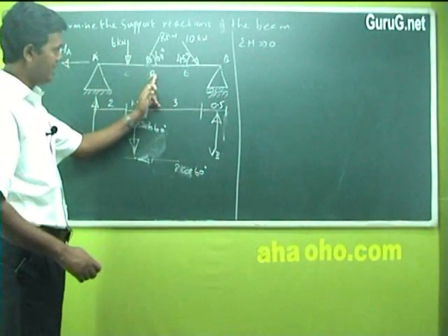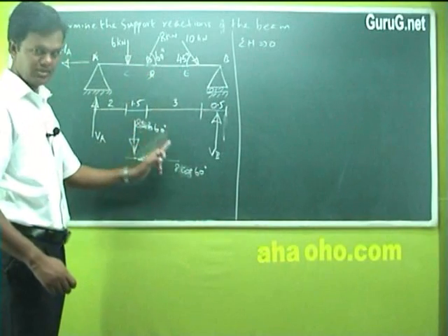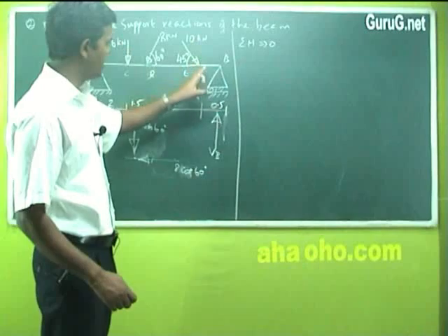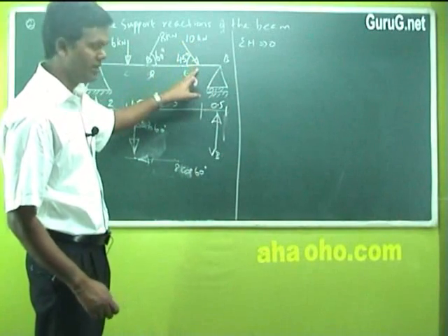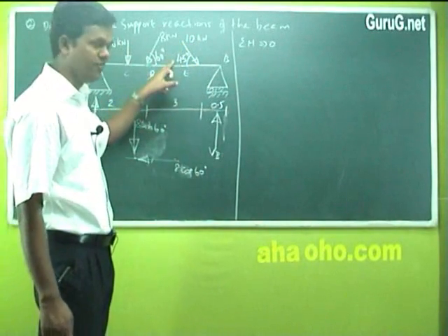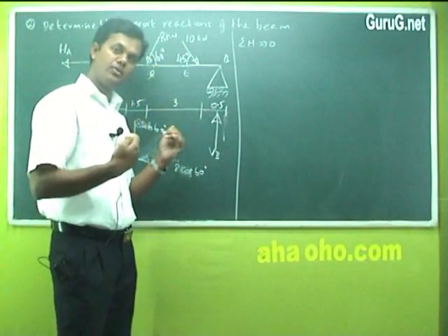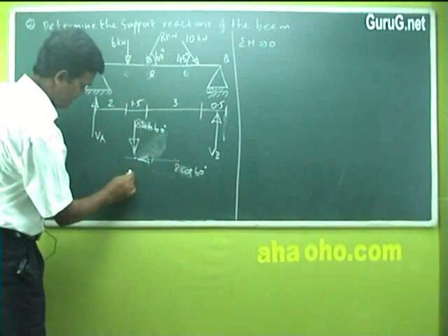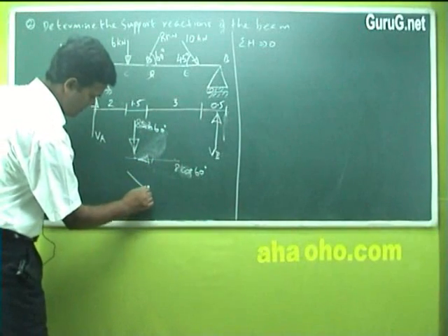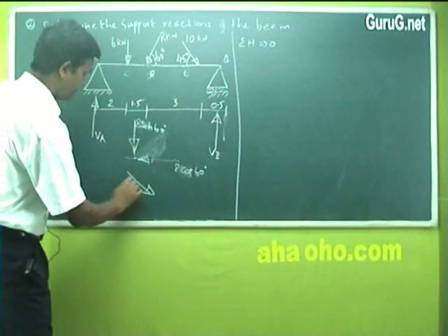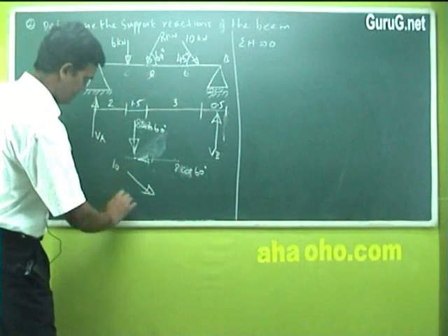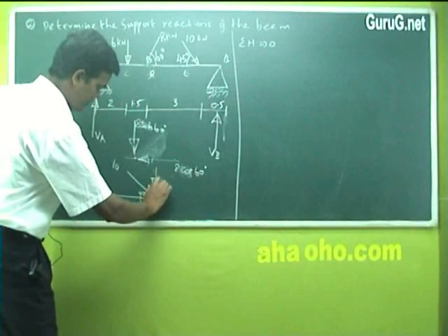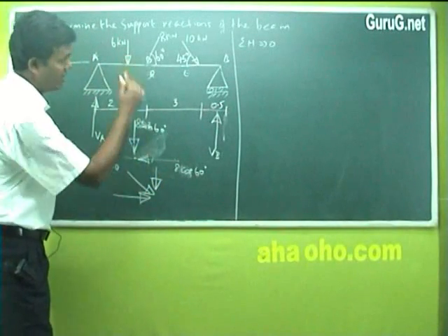Second point, at point D, you should have two forces like this. And at point, suppose E, you are indicating again this 10 kilonewton inclined force with an angle of 45 degree, which should be resolved into horizontal and vertical like this. So what will I do? I am just writing the nature of this. Is it okay? This is 10 kilonewton. Introduce one horizontal and one vertical. The angle was 45 degree.